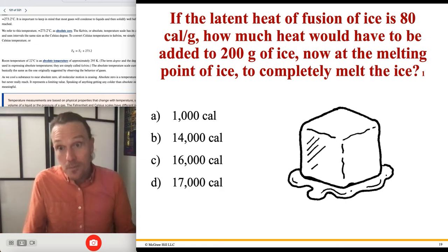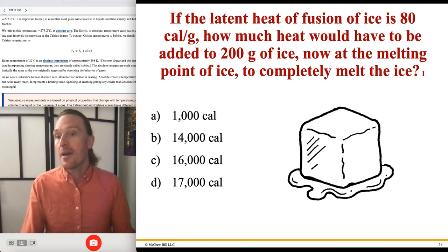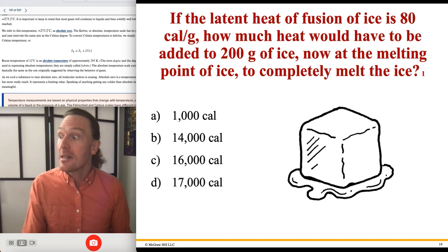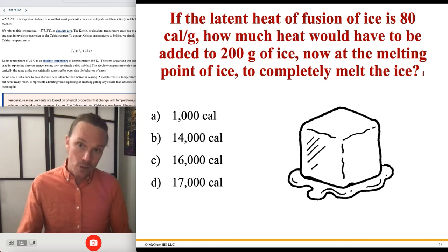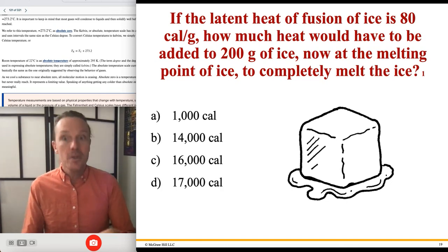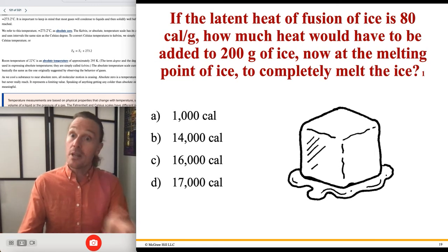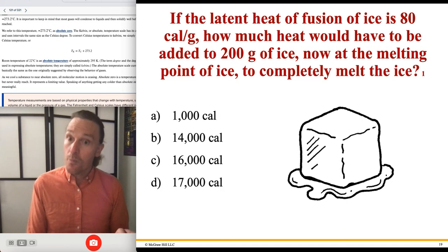But any phase change, those being from solid to liquid, which is melting, or vaporization, you go from latent heat of vaporization, latent heat of fusion. The latent heat of fusion is the one that refers to the change from a solid to a liquid, or from a liquid to a solid. So the latent heat values that you look up in the table always refer to both ways.